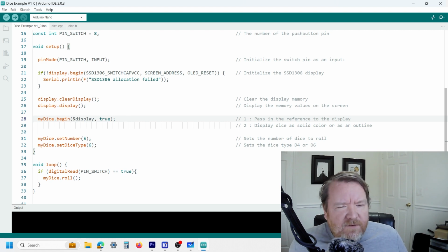So I believe that there is an overflow issue somewhere within the Adafruit OLED display driver, which, when you start running out of memory or getting low on memory, causes some of the screen memory to get corrupted.